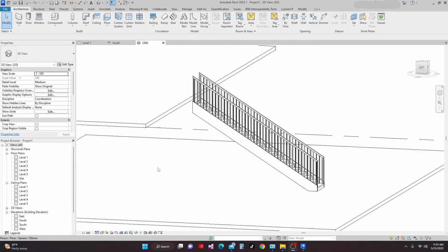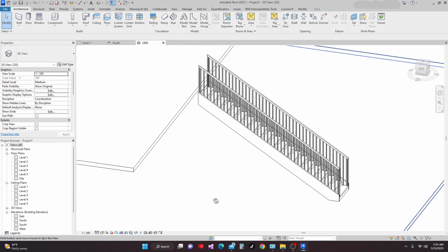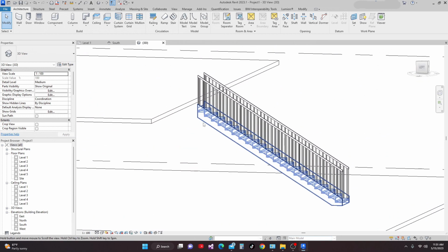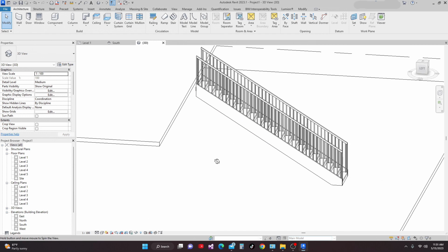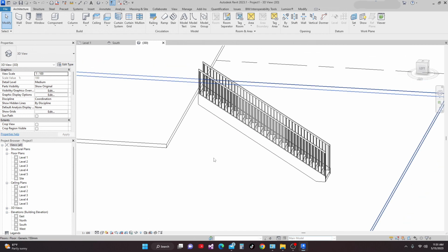Okay guys, as you have seen here in our drawing, this base offset and top offset is adjusted. What I am emphasizing here is that the overall height determined by the base and top level will be equally divided into risers. Because of this, stairs remain associated with the datum object. If the datum objects are adjusted or the offsets are redefined, the stairs will be automatically adjusted by the calculation rules.